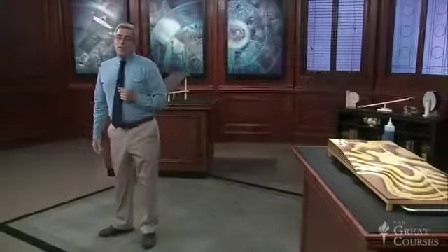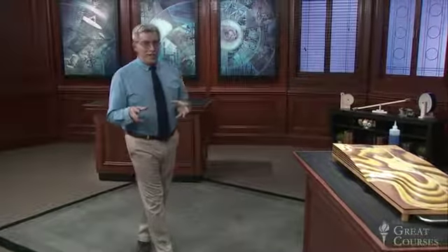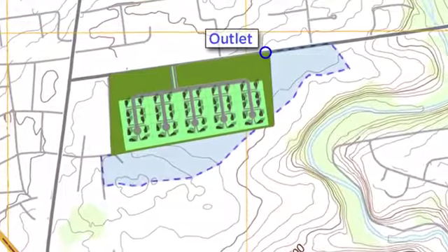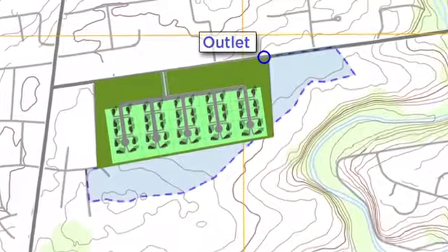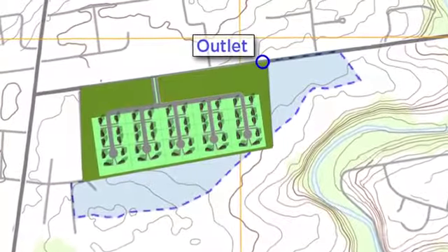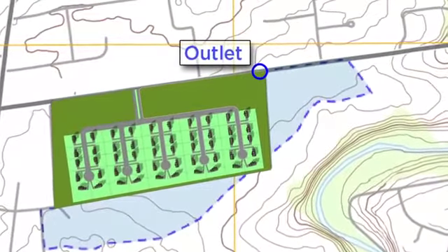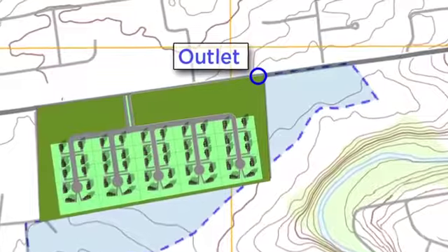from view. So now our project site has a shiny new storm sewer system to keep water off the streets within the residential development. But we still need to contend with a second major challenge, the substantial increase in discharge at the outlet. If we don't do something about the 1,000+ gallons that will accumulate here every second during the design storm, it's surely going to flood the main east-west road.